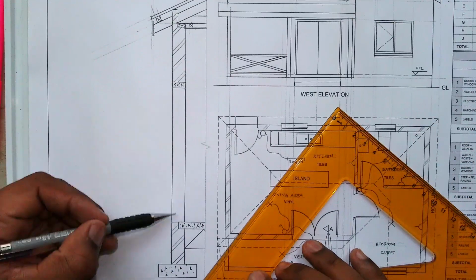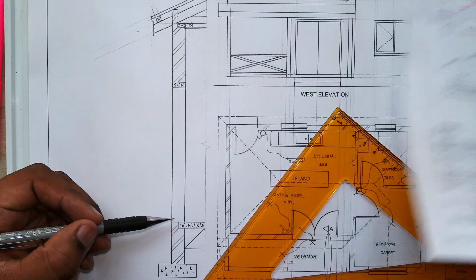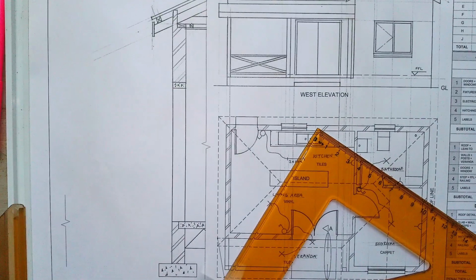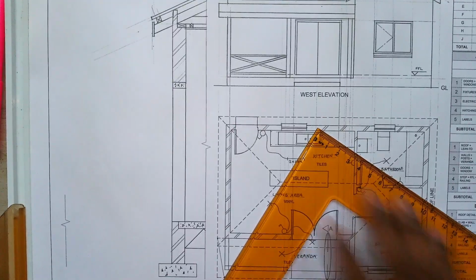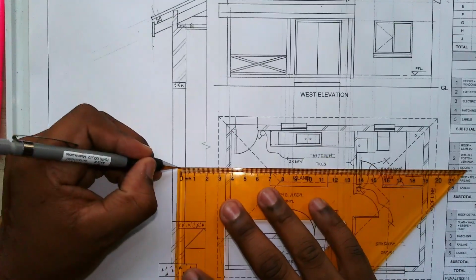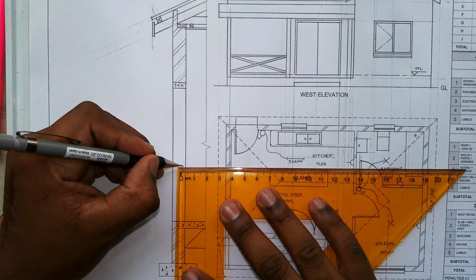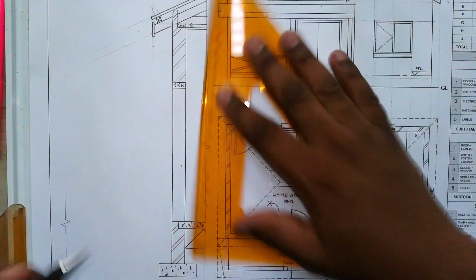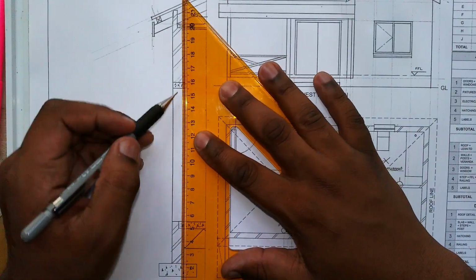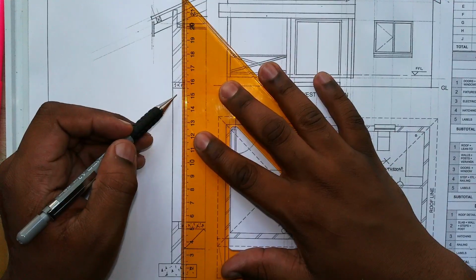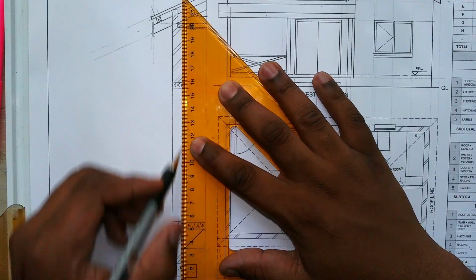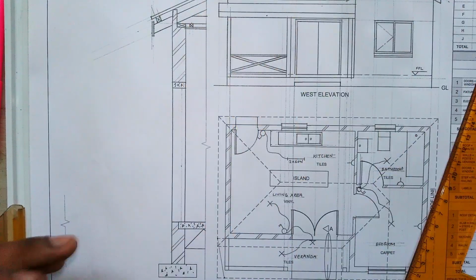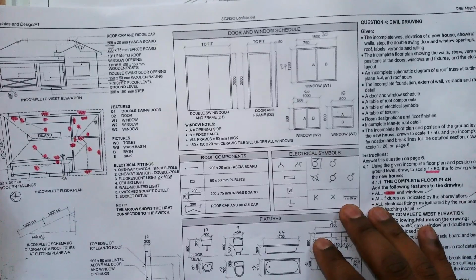Okay, so the opening there, obviously I have to draw the double swing door. All right, okay, so the thickness of the door, remember, is 50. When I divide 50 by 20, I get 2.5. So I'll measure 2.5 from this line going in. It's there. So I'll just draw a line there. Okay, light construction for now. I just want to double check there.